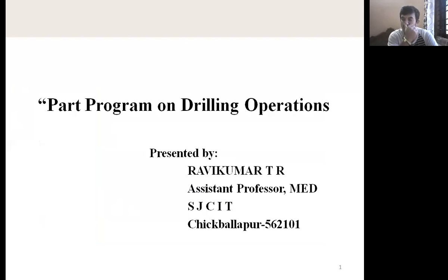Last class we discussed the part program and drilling operation. Drilling is nothing but a process of producing a hole on a workpiece. There are many drilling operations. First, producing a hole is called drilling, or enlarging a hole is called boring, or enlarging a hole only on one side of the drilled hole is called counter boring, right? Or if you want to make a helix form in an already drilled hole, that is called tapping, right? If you want to finish the hole, that is called a reaming operation. Those are the drilling operations.